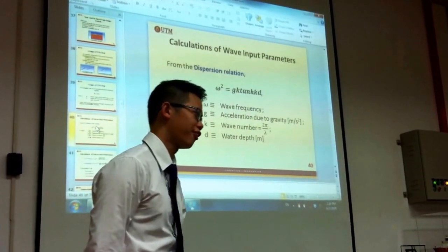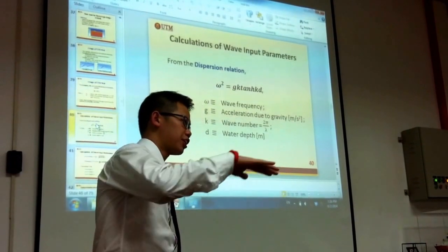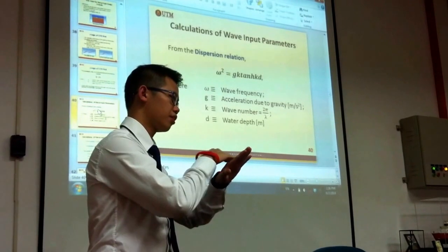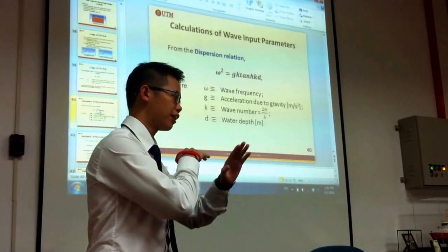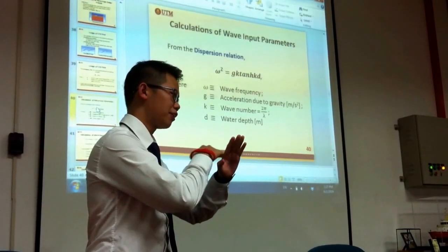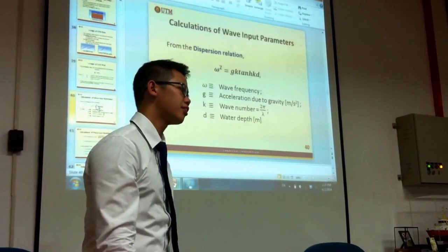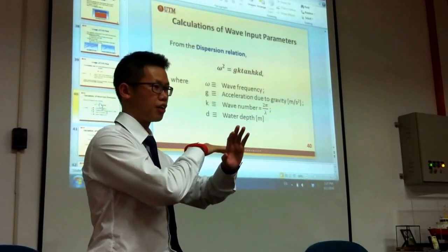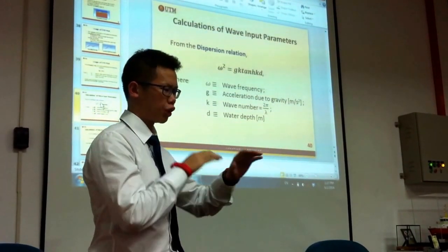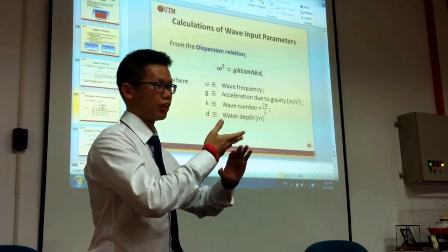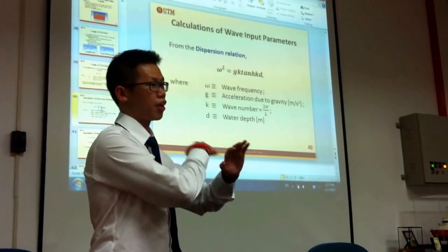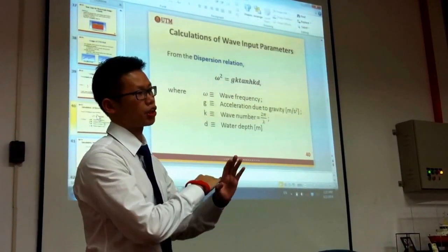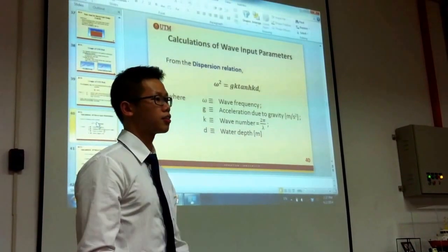That's why I was telling Dr. Koro this now. Because I vary the ramp angles, but I fix the wave parameter. So from there I can know which ramp angle yields the highest overtopping rate. So that's why in my recommendations for future work, they can try to vary. Since I already have a guideline for which ramp angle will yield the highest overtopping rate, they can then vary the wave parameters from there. Because I fixed that one parameter as an average for the local wave conditions.